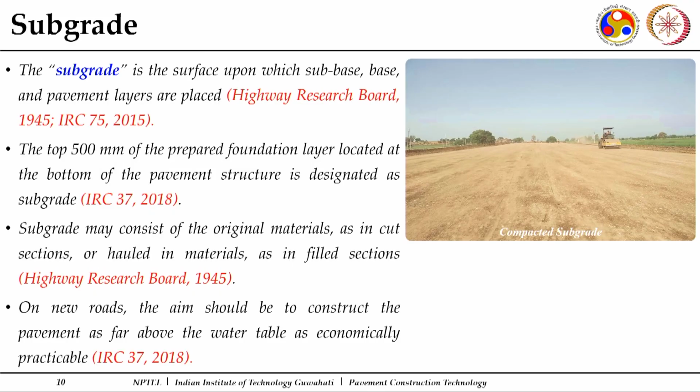So there are chances that your structure may fail because of this particular embankment. That's why it is always preferable, when these waterlogged areas are there, that you give a flatter slope. Now we need to make things ready for the subgrade to come up over it, because we will consider subgrade as the foundation of your pavement crust.